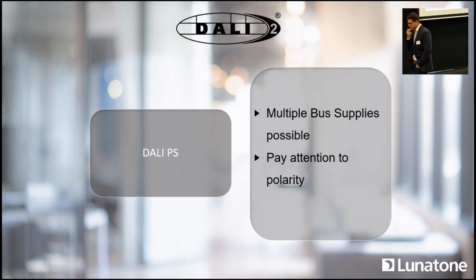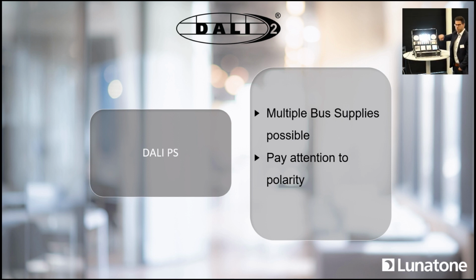So DALI power supply, what's so special, or what is new? We now have the possibility to connect multiple bus power supplies. If you remember the first example, with this device I can do 80 milliamps. Now think about an installation where the customer wants to add more devices, not another room, but another floor, like an extension of a building, and wants to use the same DALI line. Then it could come in handy that you can now add another bus power supply.